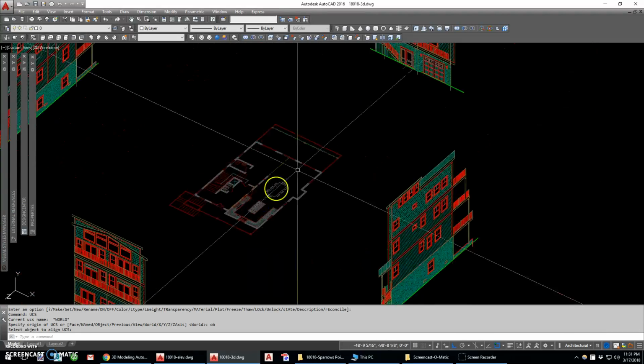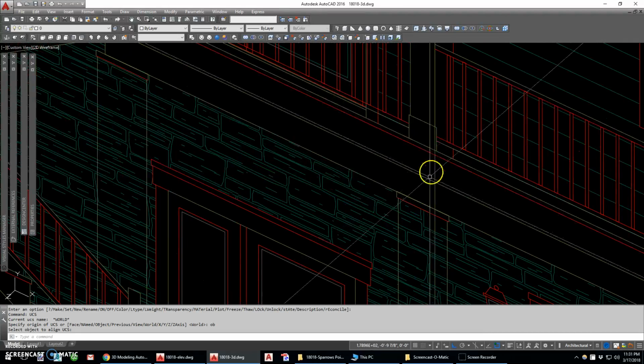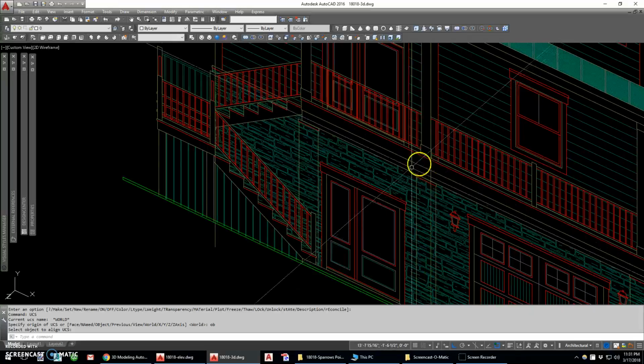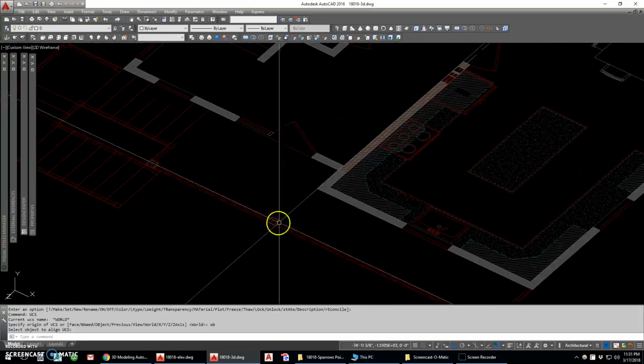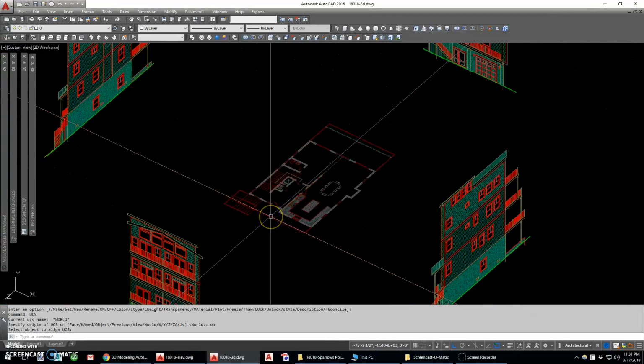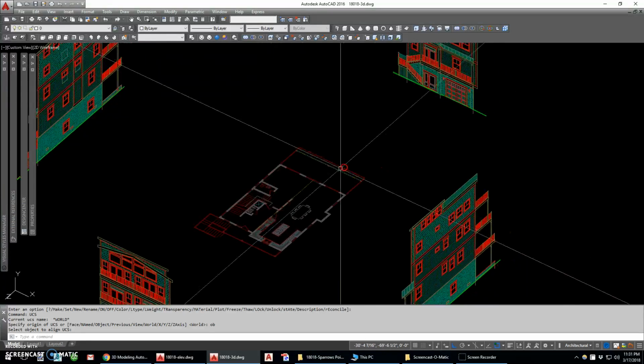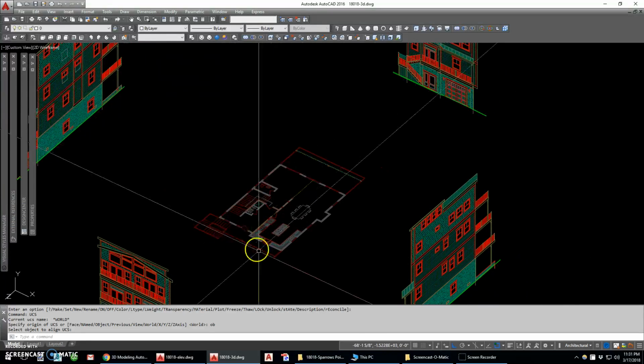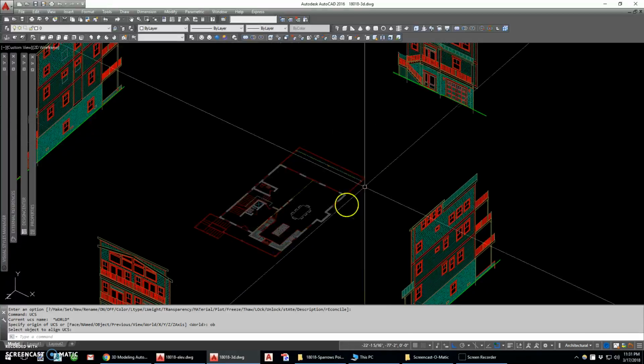Again, now as I look at the drawings, there's a break line here, which tells me that this comes out further, but as I look at the plan, there is no break line. Some minor conflict in the architect's drawings, no big deal. But I'm going to follow the plan here because I believe this more.